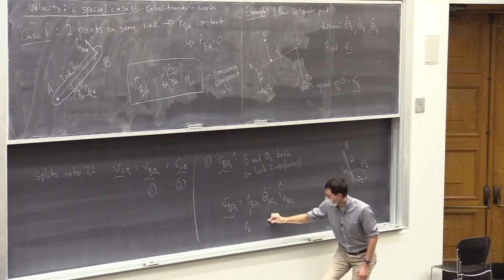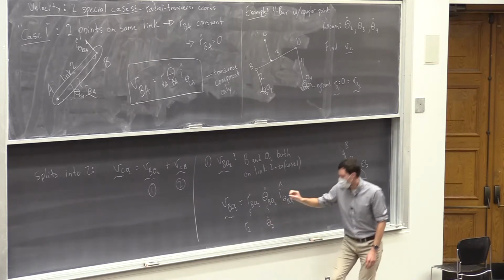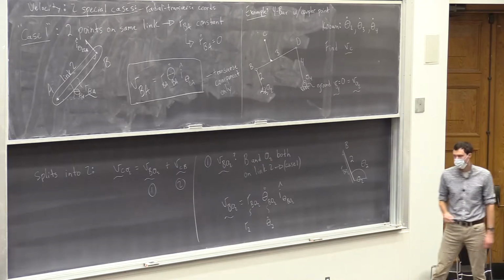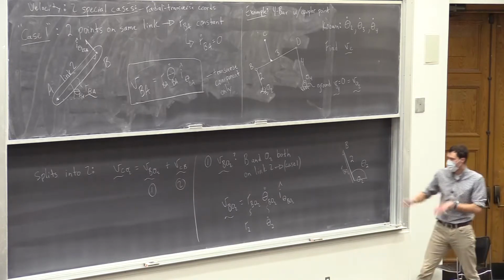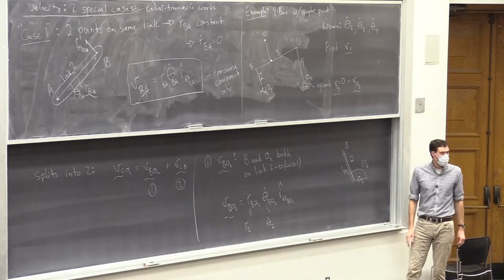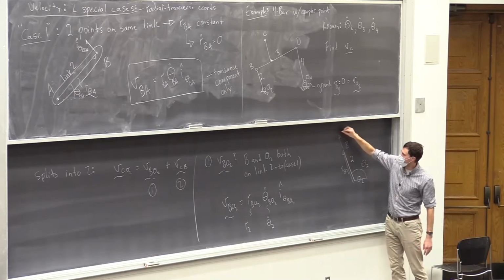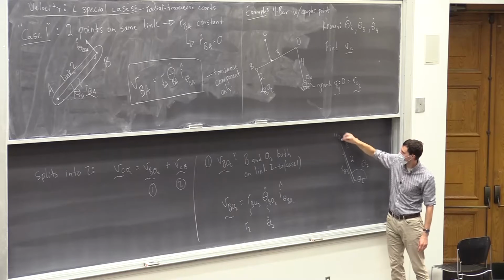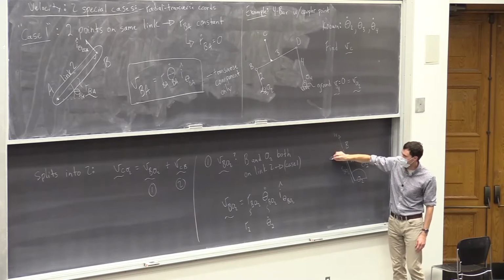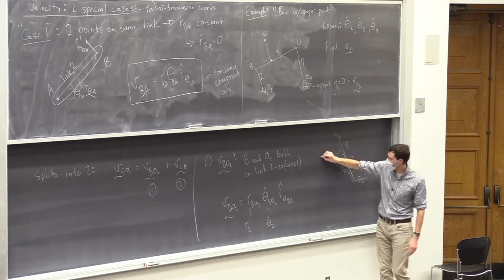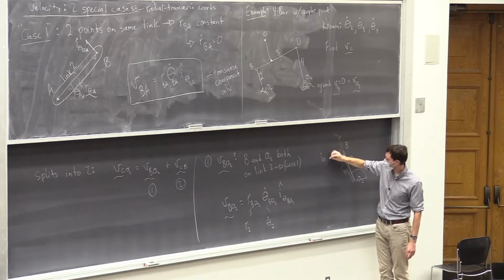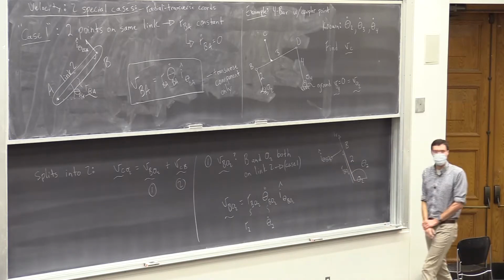So this thing we could rename theta 2 dot, rotation rate of link 2. Okay, and the last piece is the direction, which we've already found. Radial would have been out along that vector. But we want transverse, which is 90 degrees counterclockwise. So that's our transverse direction.